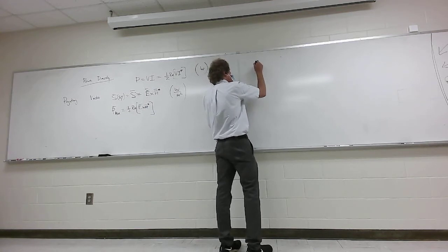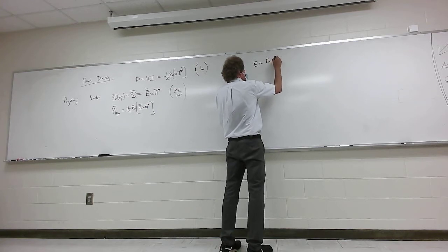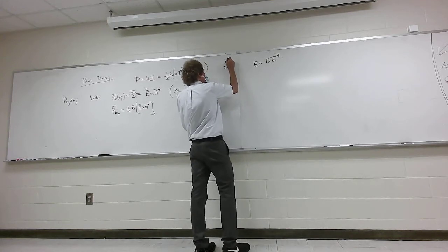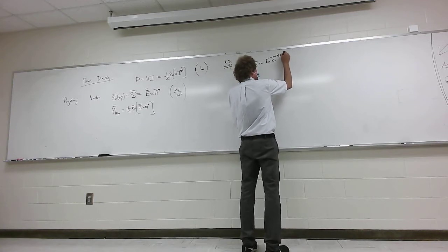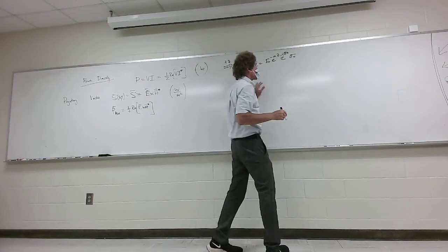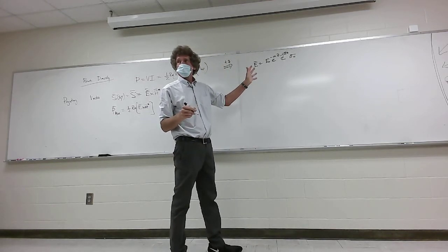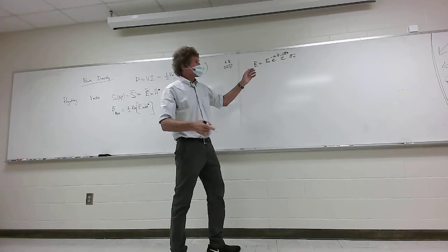We have an E field equal to some E naught e to the minus alpha z. Let's assume it's propagating in the z direction, so we're going to have plus z direction propagation. It would be e to the minus j beta z in the a_x direction. I'm going to be consistent with what he said. Y'all recognize that as the standard way we describe a propagating electric field in the x direction. This is Dr. Whitmore's choice, and I want to keep it simple.